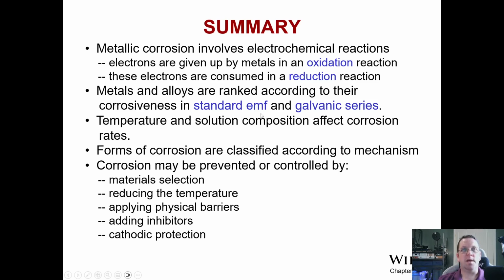So temperature and solution composition definitely affect the corrosion rates, and there are different forms of corrosion. We need to be paying attention to what materials we're picking, what kinds of operating temperatures they're going to be in, what kinds of physical coatings or inhibitors we need, and whether or not we might need to use cathodic protection for something like a structure that's designed to be in service for a long period of time. So there's a lot of design considerations that we have to incorporate.